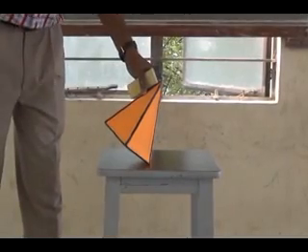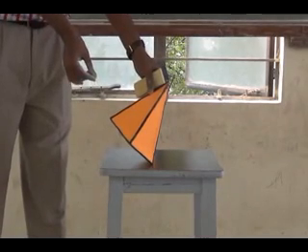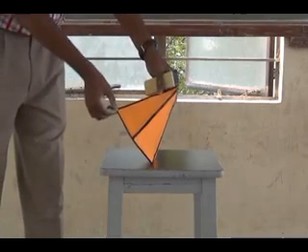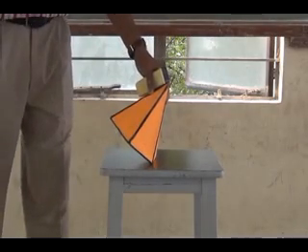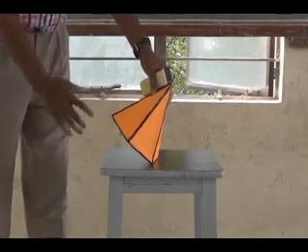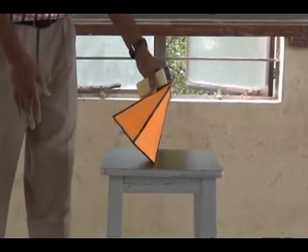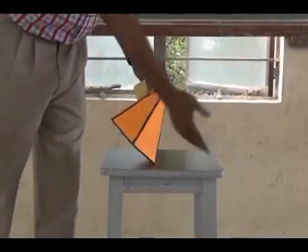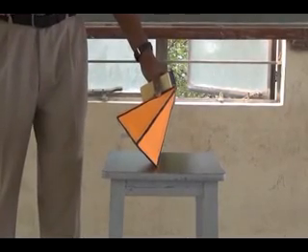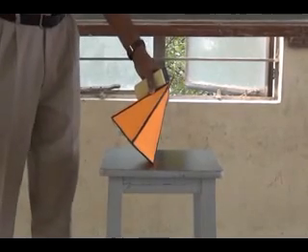And the other extreme, it is a pentagon, it is resting with the edge. A corner, the other corner will be opposite to that. That corner's height is given from the ground. That corner height is 25 mm above. If that corner is 25 mm above the ground, then how is the solid tilted? The axis of the solid is inclined to HP. Since the resting edge is perpendicular to VP, the axis is parallel to VP.